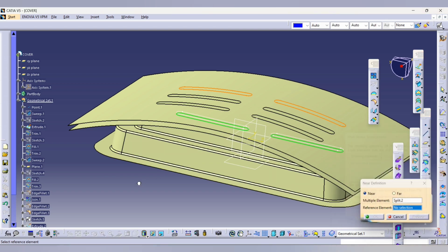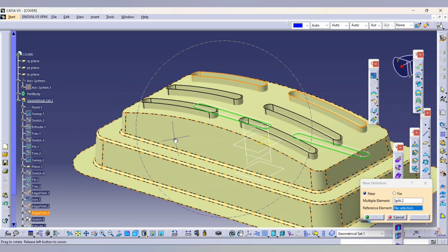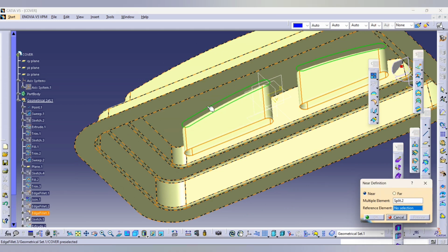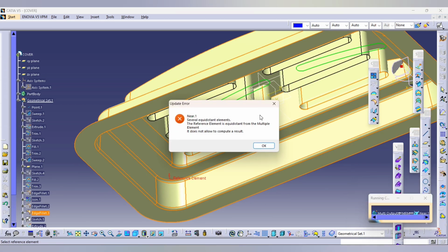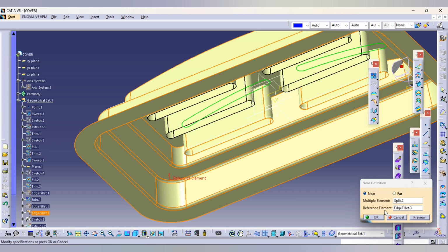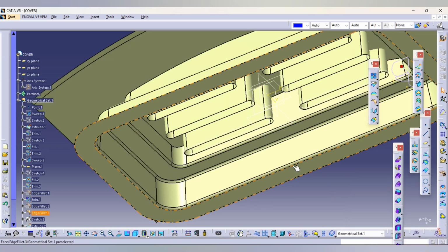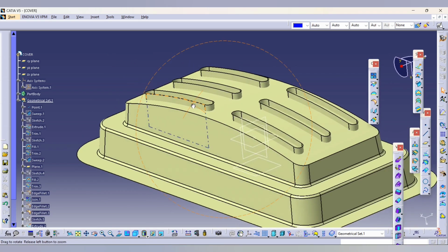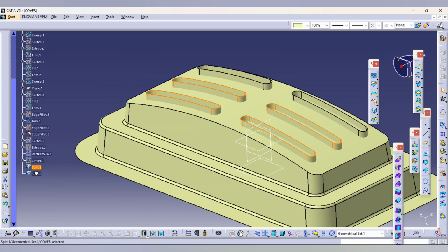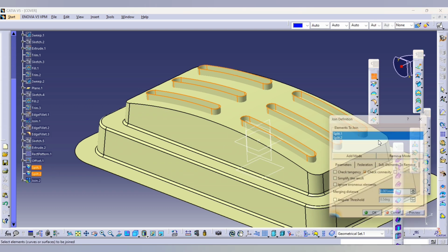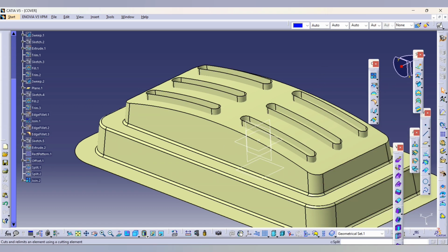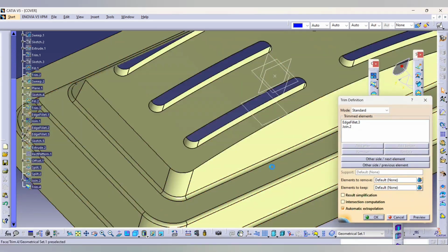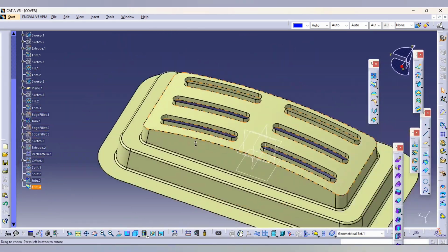Next, we'll make sure all six get joined. So we'll do the join first, before the next trim or anything. We have to cancel this. So successfully we have trimmed everything. Now we have to split everything, and trim with the base cover surfaces. Before that we'll join everything and start the trim. So here the inner surfaces are trimmed, and now this is the final product.